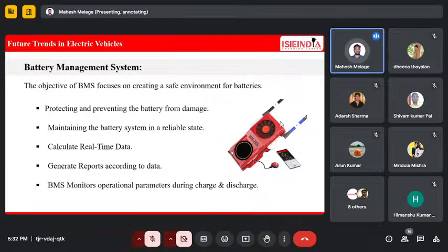So we can charge the battery to 100%. But then the 50% cells reach only 70%, and the 80% battery cells go to overcharge. All right, clear. So this is the overcharge and undercharge. It will affect the battery performance. That's why we maintain the battery system.